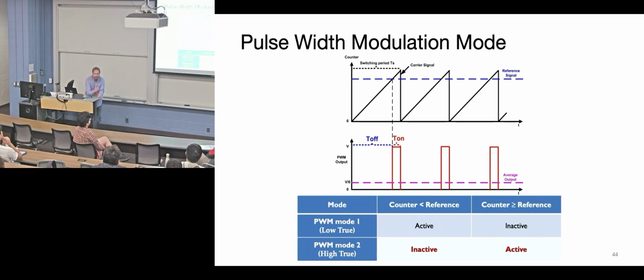So now if you can set your reload time, and you can set this threshold somehow, you could create this waveform down here showing us the T off and the T on. You're just making this decision basically. Here, the hardware automatically makes a decision to return, and now you're making this pulse train. There's a couple different modes the STM32 gives you, whether you're in PWM1 or PWM2 mode. It's just which way is the logic that you're thinking about this.